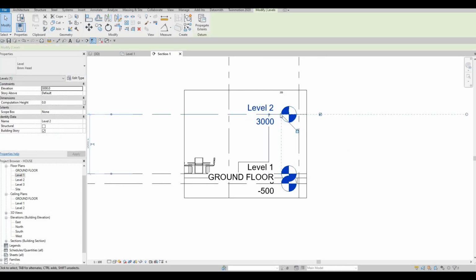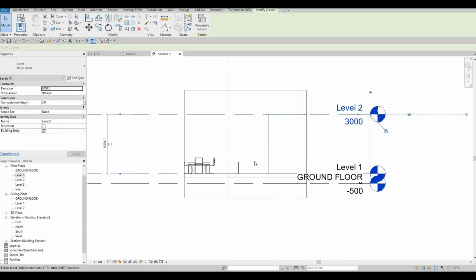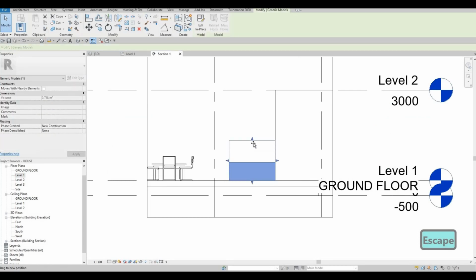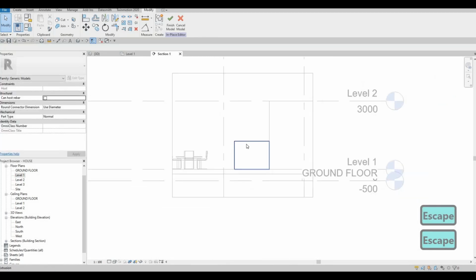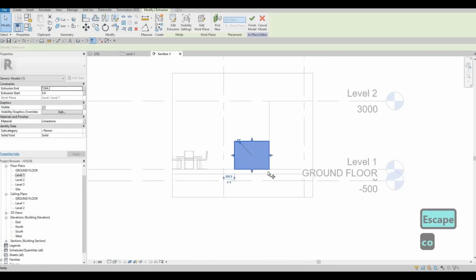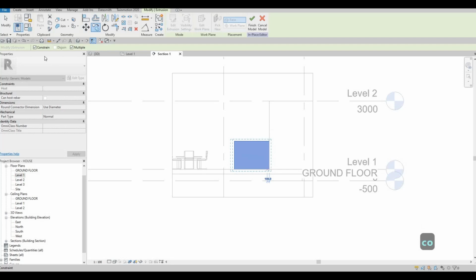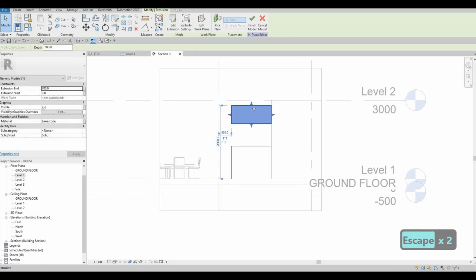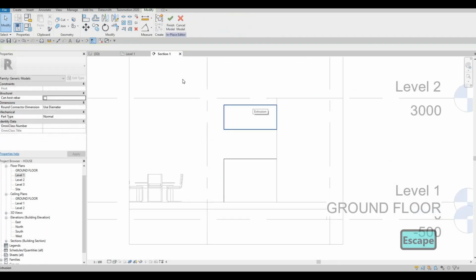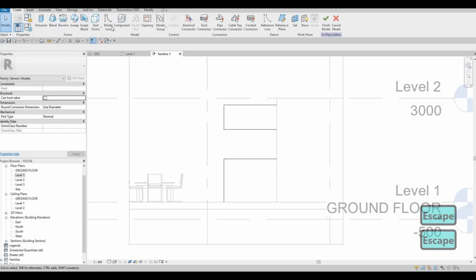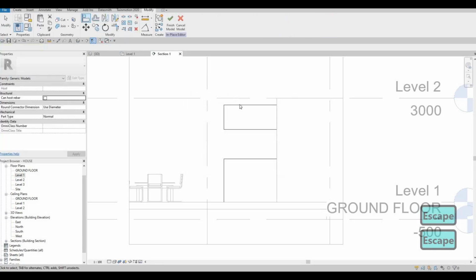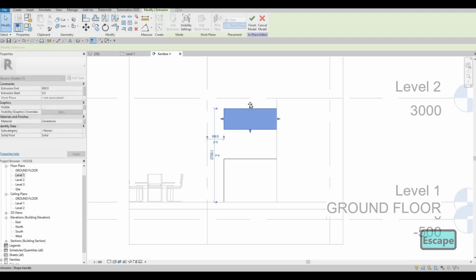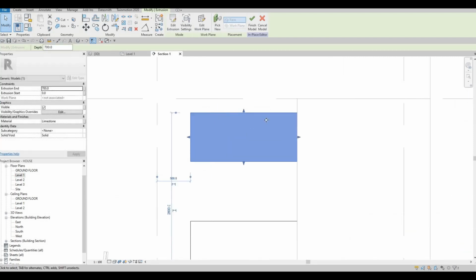Push this all text right here onto this side, and then here we could just add this one right there, edit in place, and then we need to add another one at the top. We need to remove constraint, and then here what we can have is we need to make sure that this has a 200 gap, so it should be not.